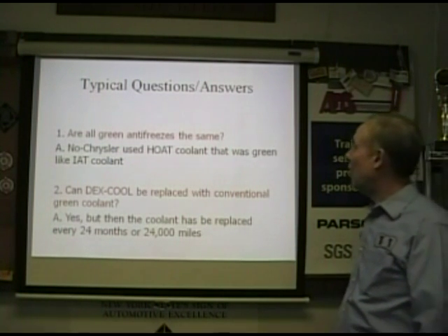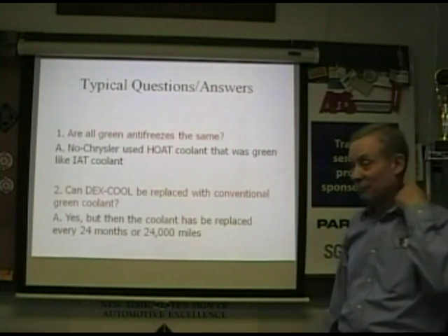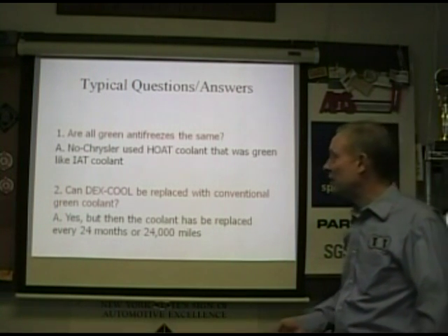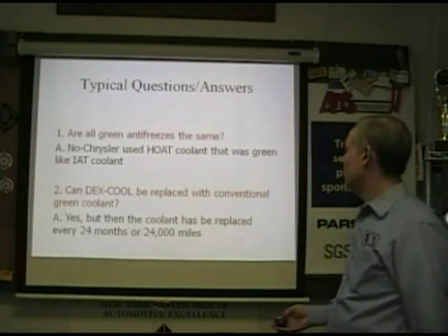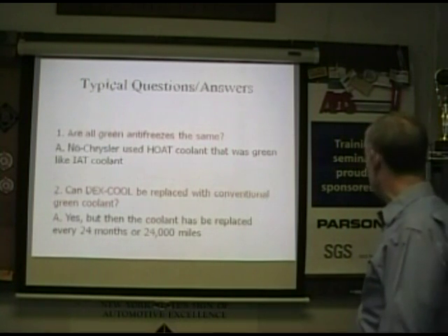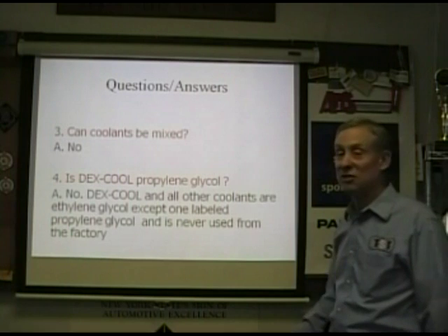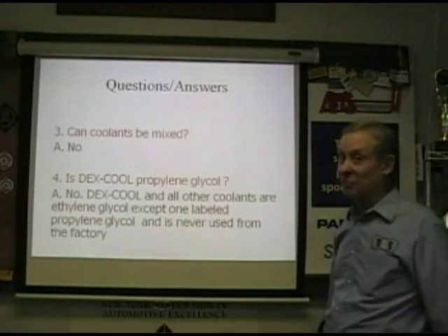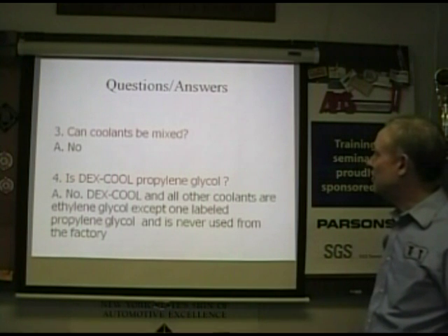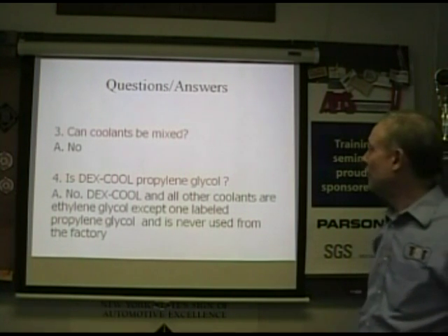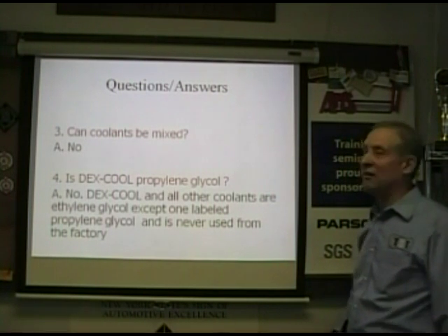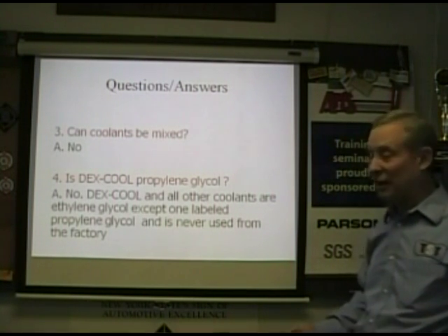Questions and answers. Are all green antifreezes the same? Obviously, no. Can Dexcool be replaced with conventional green coolant? Yes, but then you got to flush it all the time, and you got to worry about whether you flushed out the old stuff properly, because you have these incompatibilities that can be very damaging. Can they be mixed? Absolutely not. Is Dexcool propylene glycol? No. Dexcool and all the other coolants are ethylene glycol. No propylene glycol.